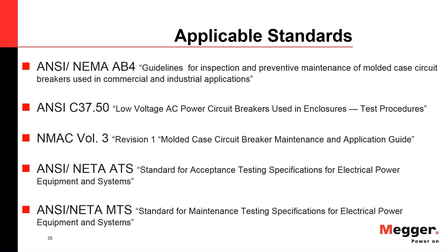Now, one could argue that on the long time test it doesn't really matter because there are so many cycles that this little asymmetry, if there is one in the beginning, doesn't matter. Technically that is true, but for any test you should always eliminate the DC component, specifically for the instantaneous test, because it will be at least an inconclusive or even invalid test.